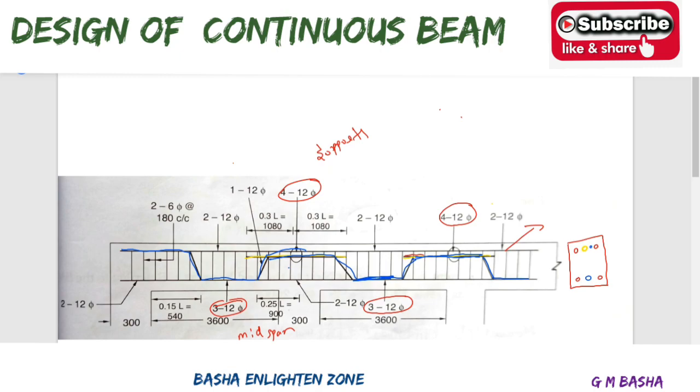They cover with full 2 bars and 1 bar at the mid spans, and the same bar covers the interior supports in tension. Like this they are providing cranks also. Another bar they keep as a half bar wherever it is required. So this is one procedure of how they provide the bars. And for cranking also, according to the standard rules, like 0.3 times L, here 0.15 times L. So we have to follow these rules and conditions.